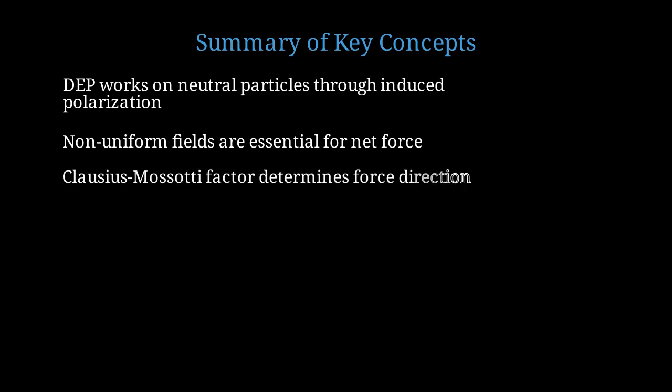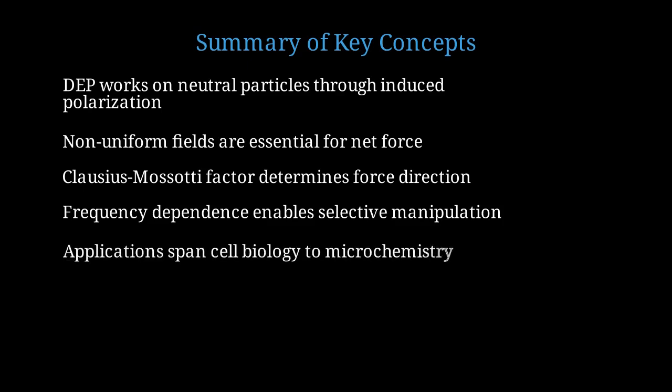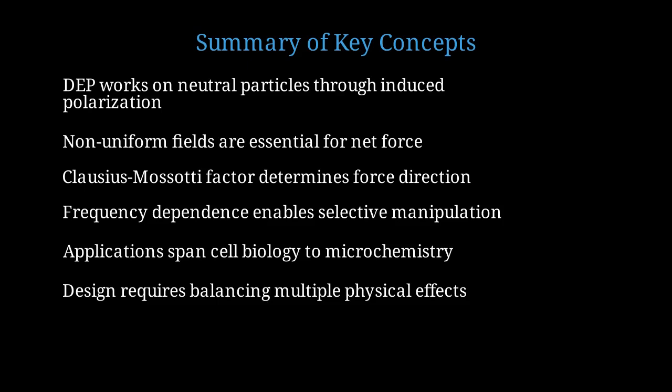Third, the Clausius-Mossotti factor determines whether you get positive or negative DEP. Fourth, frequency dependence is what makes DEP so powerful for selective particle manipulation. Fifth, applications span from fundamental cell biology to practical diagnostic devices to programmable microchemistry. Sixth, practical device design requires careful balancing of DEP forces, electro-osmotic flows, heating, and other physical effects.